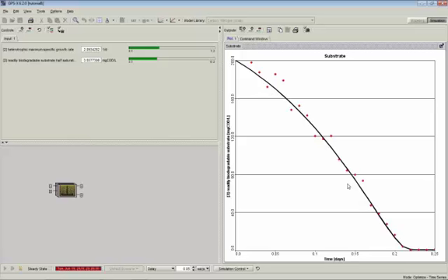So eventually this is going to stop based on a termination criteria. There are several of those that you can control. Basically, when the changes in the parameters become very small, or when the value of the objective function itself becomes very small, meaning that the change in that is small, and it's not improving its guesses over time, then it brings it to a halt. It can also specify a maximum number of iterations as well.